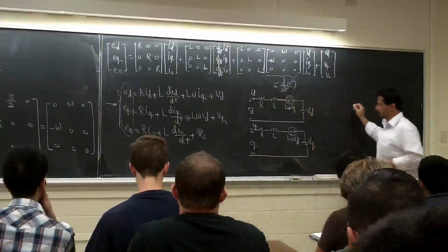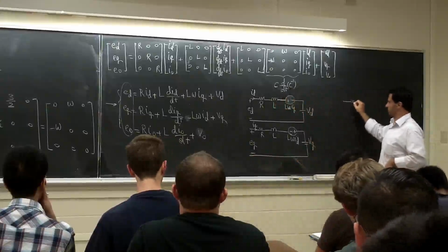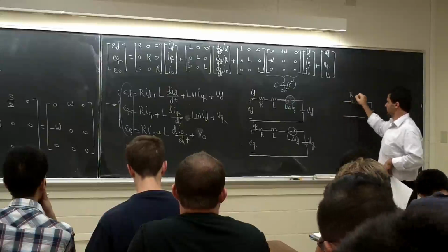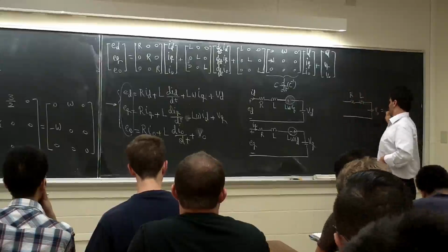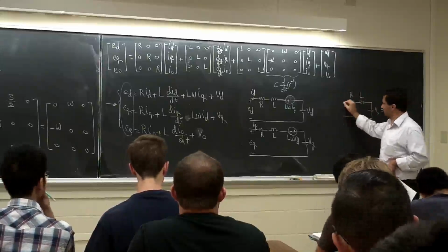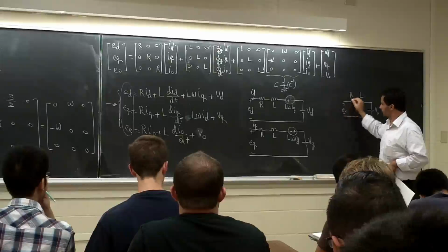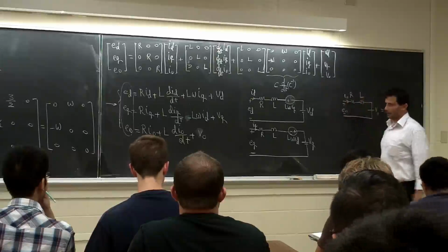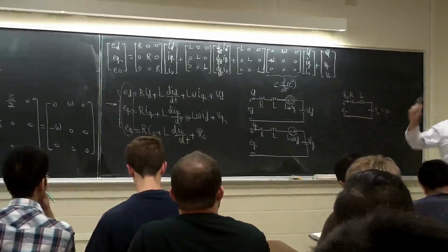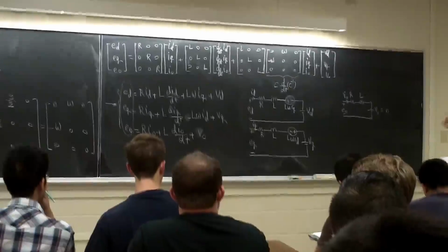And the O is going to be like this. O is simple. V_O is 0, right? It's a balanced system. V_O is 0. These are the three equivalent circuits of that ABC system in the DQ frame.